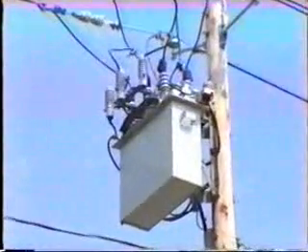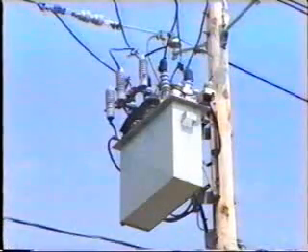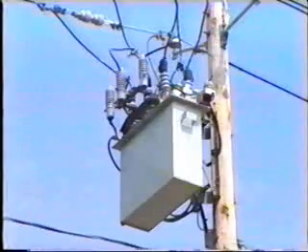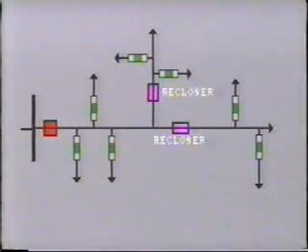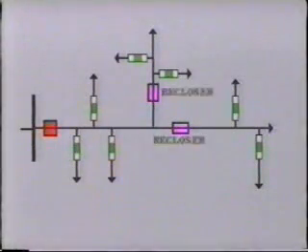On distribution systems, another more direct reclosing arrangement is often used in addition to the reclosing relays that we've been talking about. The device in question is known as a recloser, and it is usually installed in the line itself at some remote distance from the feeder breaker. Several reclosers may be installed, particularly at points where different sections are tapped off.